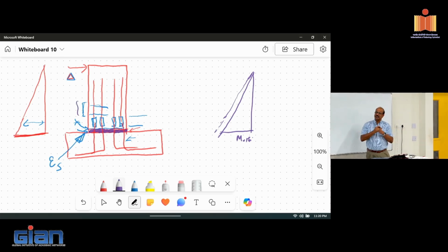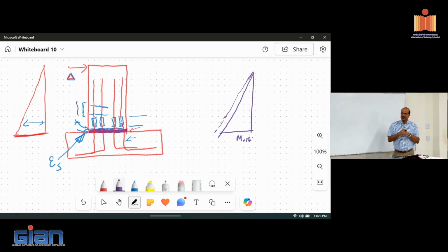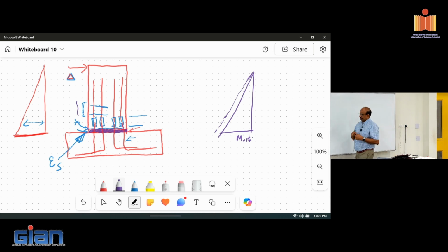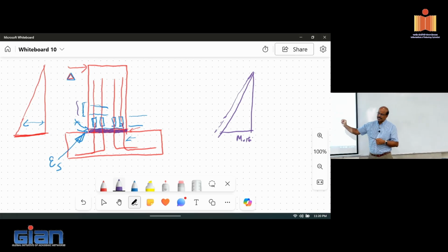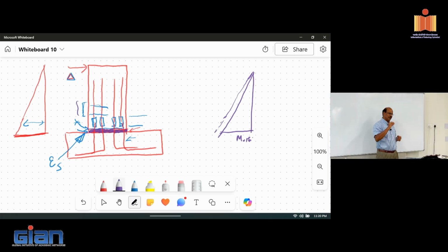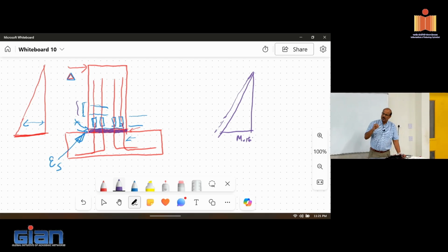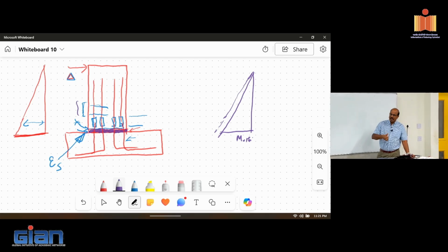So your concentration, in the New Zealand earthquake, this was very visible. They developed basically all of the cracks at the interface. And when you develop cracks completely at the interface, the strain buildup is faster. When the strain buildup is faster, a lot of things happen. This happens obviously in walls which were designed with minimum reinforcement, so there are not a lot of dowels going through.